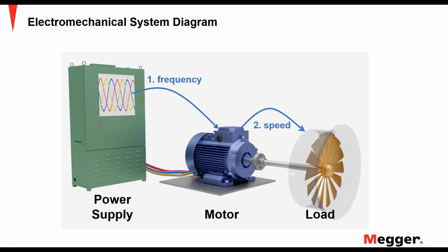And because we have a rotor installed, that rotor is constructed into bars. It has shorted bars, basically a ring that looks similar to a squirrel cage or a hamster cage. You might know a hamster cage. I've never seen a squirrel cage. And those bars are shorted. So we put that inside that spinning electromagnetic field. We're going to induce a voltage into the rotor. We'll have a current flow due to the shorted bars, and it chases that electromagnetic field.